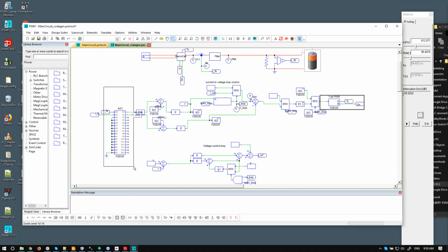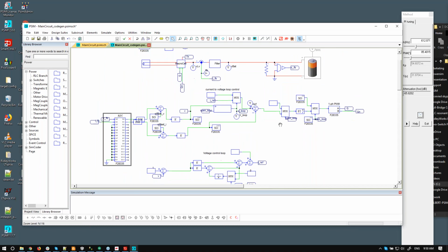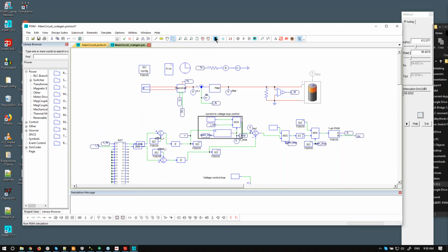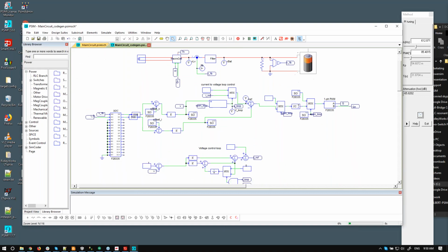Over here, we're doing an ADC sampling setup, and then I've also set it up so that there's some logic in here, so I can run it with just open loop to start with, and then I can also set it up so that we close the voltage loop. We run in constant current, and then I close the voltage loop once we hit a specified value. Let's see if this one will want to simulate. So this one should be simulating, right? Okay, so this one does simulate.